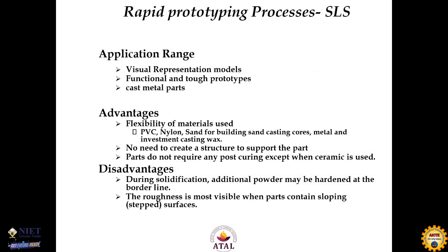There are some disadvantages and limitations of SLS as well. During solidification, additional powder may be hardened at the borderline. The roughness is most visible when parts contain sloping or stepped surfaces.